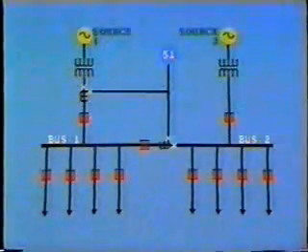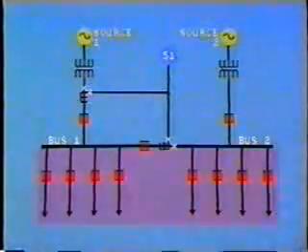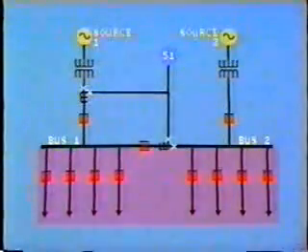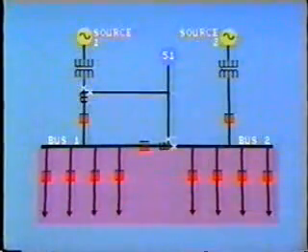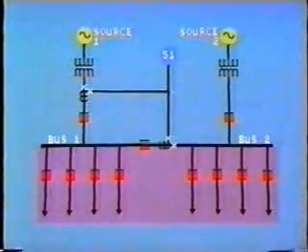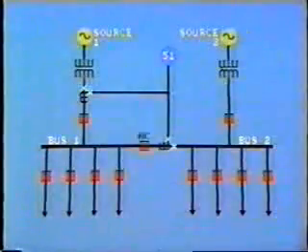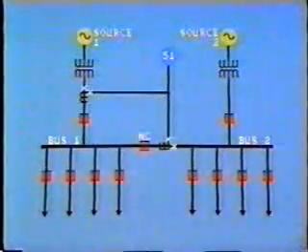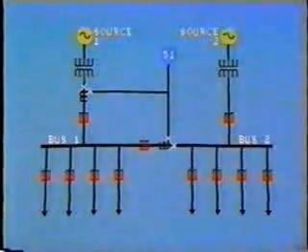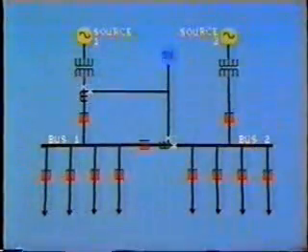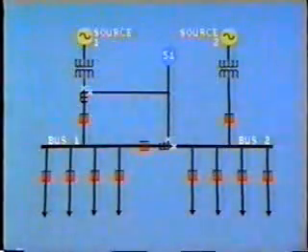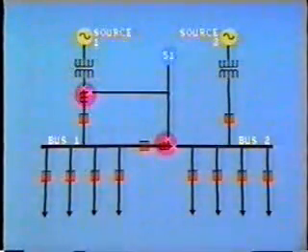The buses are fed from 2 separate sources and feed 8 outgoing radial feeders. As the feeders are radial, the current will not reverse in the case of a bus fault. On this particular system, the bus tie is normally closed. Partial differential protection for bus 1 is provided by the time over current relay 51 connected to these 2 CTs,